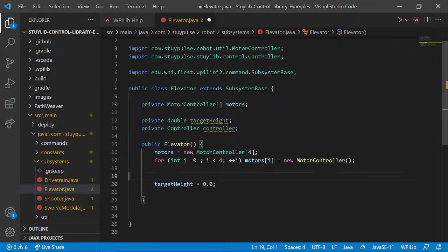So then based on what we learned, if I characterize an elevator, I'll get feed forward KS, KV, KA, and I'll get KP and KD from the feedback analysis. So I'm going to use PID and feed forward and a motion profile because it's position.